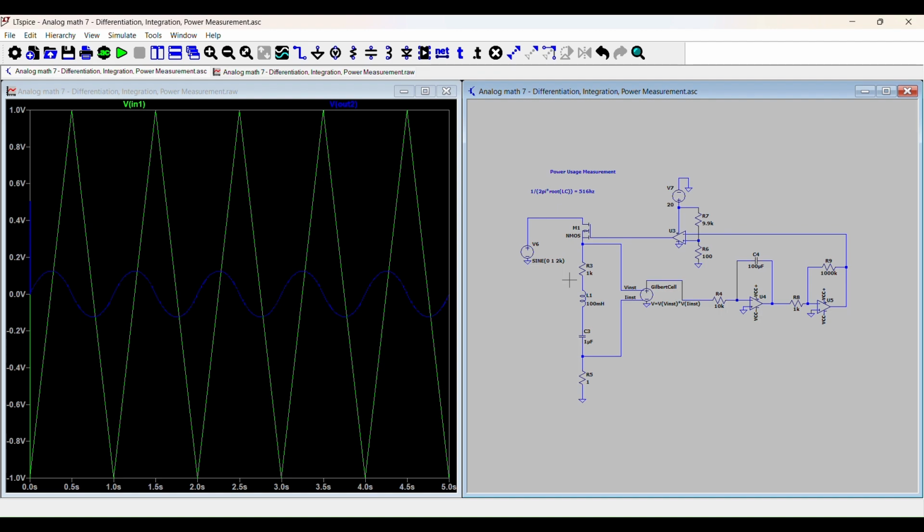When you measure power in a reactive component, a component with capacitors and inductors, which have reactance, you cannot just multiply the RMS voltage by current because they may not be in phase. Once you have reactance in a circuit, it can push the voltage and current across them out of phase, so that every time the voltage is low, the current is high, and vice versa. Even if the RMS current and voltages are very high, the actual power output could be very low because of the phase difference.